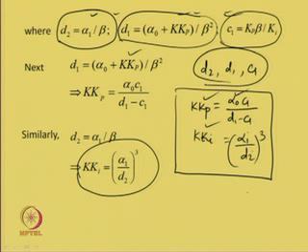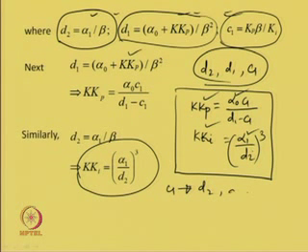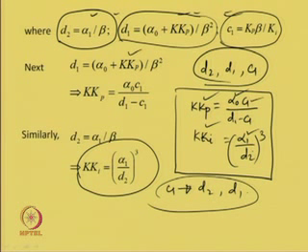Since alpha0 is known, alpha1 is known, then for any given C1 using the standard form, the standard coefficients D2 and D1 can be obtained. Thus, C1, D1, D2, all those quantities will be known to us, thus enabling us to estimate the unknowns Kp and Ki.